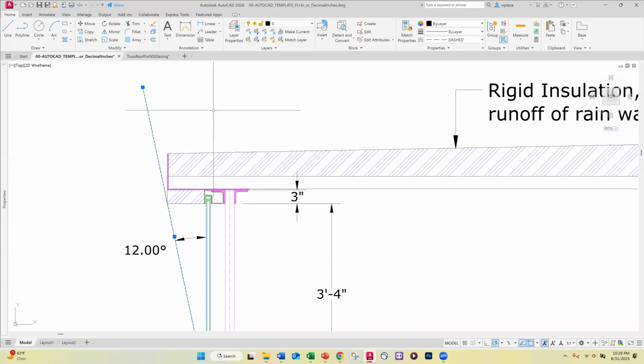It could be an angle, but nobody rolls an angle with a thin wall that's that large and unequal legs. You just can't get that, but you can get sheets of 1/4 inch thick or 3/8 inch thick steel plate and have them bend it to provide this structural function.